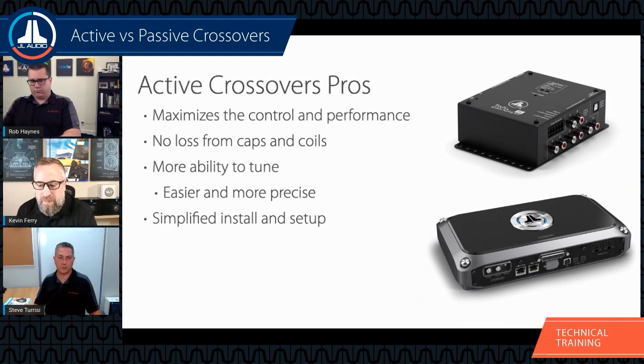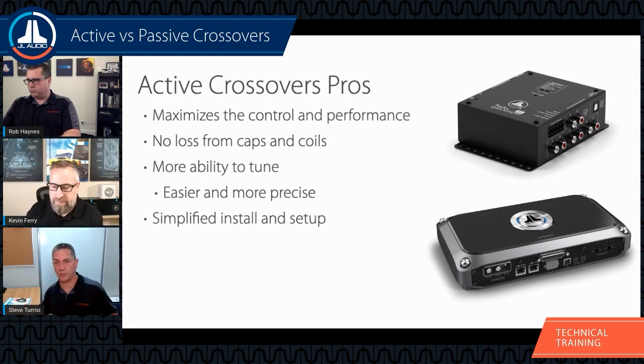Let's simplify everything and keep it in one location, and we can set it all up. Obviously, if you're using a DSP, you can do it all on the computer, or you just do it with the switches on the amplifier. Tuck the amplifier away, sit up front, and listen. Tone controls, I'm okay with up front, but everything else, let's just keep it in the back.